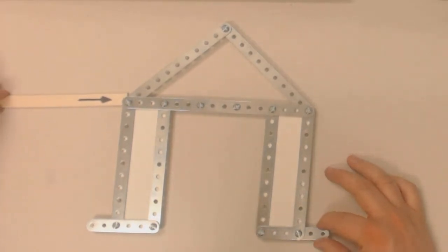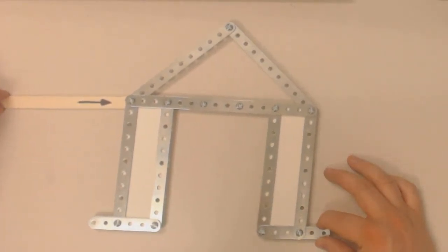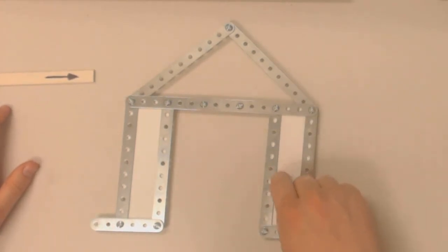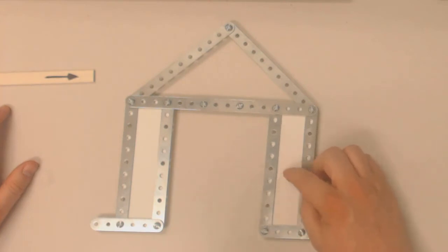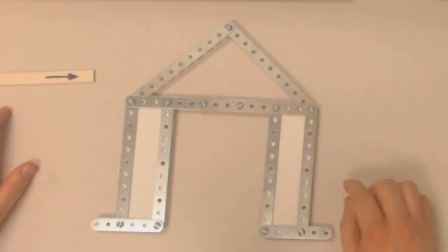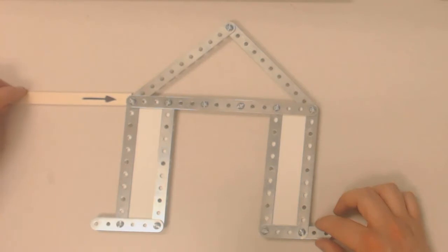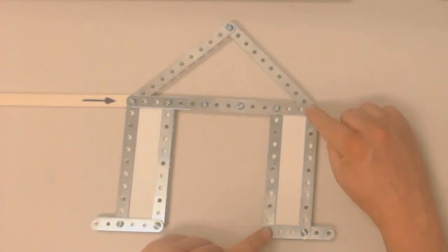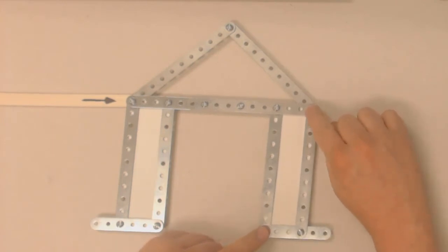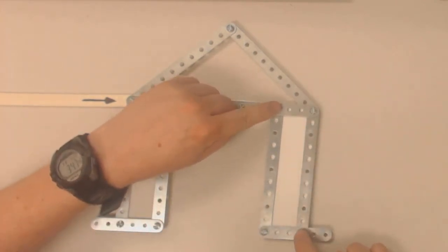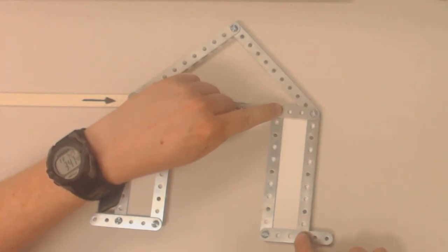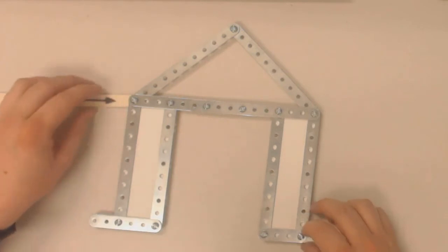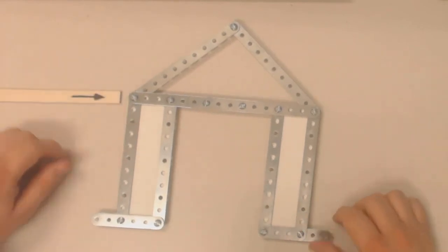And so as this force is being applied, what restrains this whole house is not just the stiffness of the shear panels, the plywood, but also the connections. Because if the force is being applied this way, then these two connection points are being pulled away from each other, and then these two connection points are being pushed towards each other. So if you push this so hard that connection gives, then this whole thing fails.